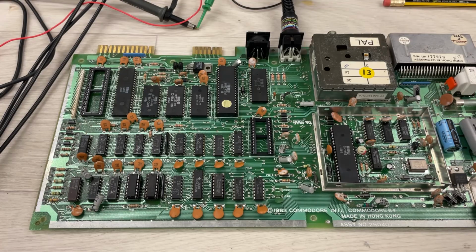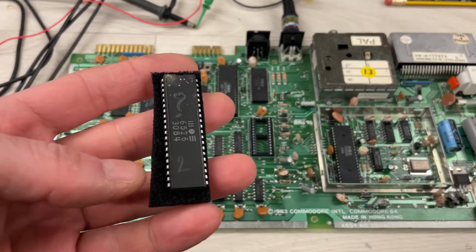Now, regarding the keyboard problem, again, the test cartridge showing the timer on CIA number 1 is not working. From my probably incorrect understanding, if the timer is not working, the CIA is not scanning for keys. And I guess it's also responsible for blinking the cursor on screen. So I happen to have one which is probably partially working.